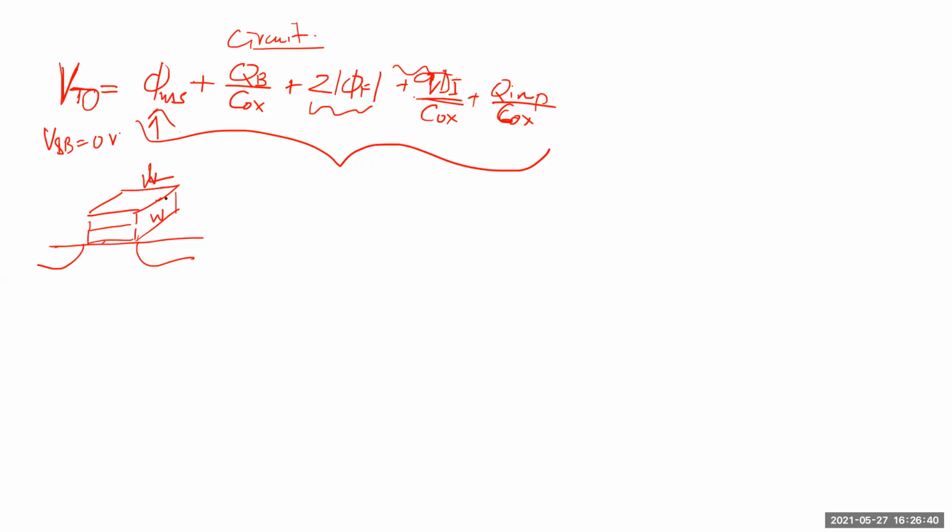I am trying to say that we can only change the COX value. Now, again, COX is also fixed. You remember T ox is, let's say for 0.18, about 2.7 nanometer. I think that's what we calculated yesterday. But this is fixed by the process. Once you decide you want to use a 0.18 process, as a designer, you can't do anything about it. So these are all process parameters, right?